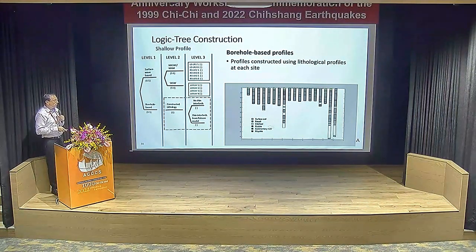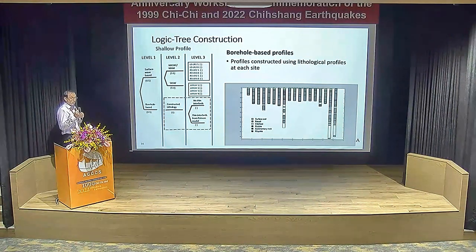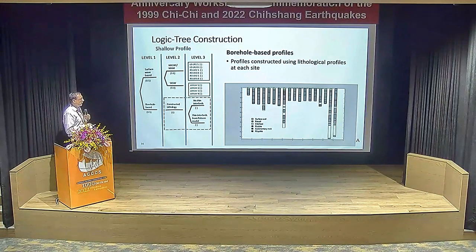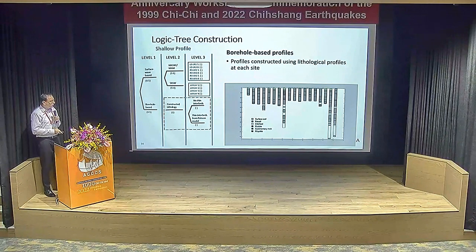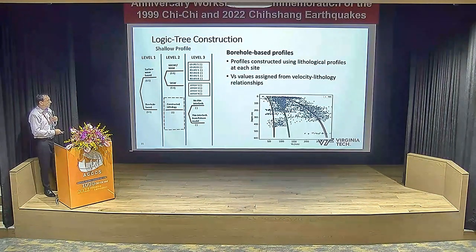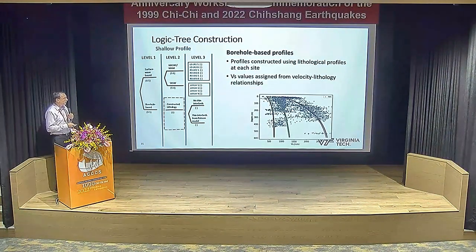So this will represent continuous interbeds, whereas these very thin interbeds, while they are present all over the site, are highly discontinuous. So we had a model where we didn't include the thin interbeds, and another model where we included these thin interbeds using a Poisson model.